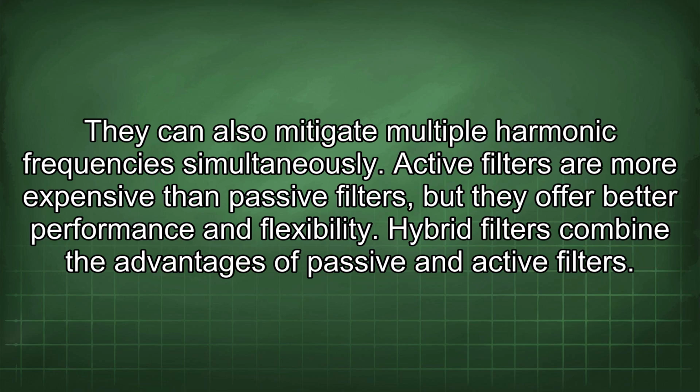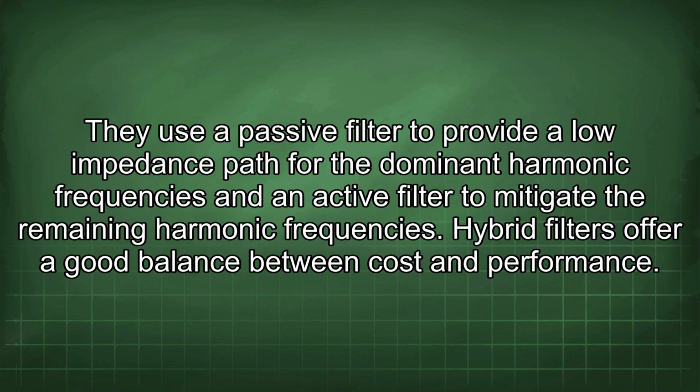Hybrid filters combine the advantages of passive and active filters. They use a passive filter to provide a lower impedance path for the dominant harmonic frequencies and an active filter to mitigate the remaining harmonic frequencies. Hybrid filters offer a good balance between cost and performance.